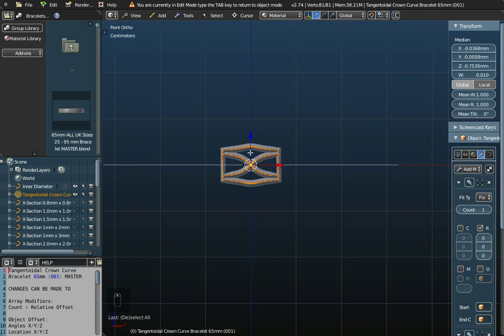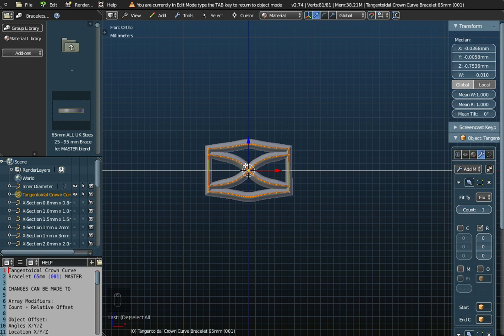Now what I'm going to do is actually stretch this object out in the X direction. And we can do that by pressing S on the keyboard for scale. If you look at the top of the screen in the toolbar, it says scale X1, Y1, Z1, proportional size 1. Well, I want to scale it just in the X direction, that's all. So I'm going to press X on the keyboard, and you'll see in the toolbar it says just scale 1 along X, smooth proportional size 1.